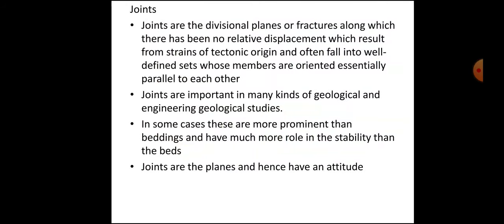Joints are the divisional planes or fractures along which there has been no relative dislocation, which result from strains of tectonic origin and often fall into defined sets whose members are oriented essentially parallel to each other. Joints are important in many kinds of geological and engineering geological studies. In some cases, these are more prominent than beddings and have much more role in the stability than the beds. Joints are planes and have an attitude.